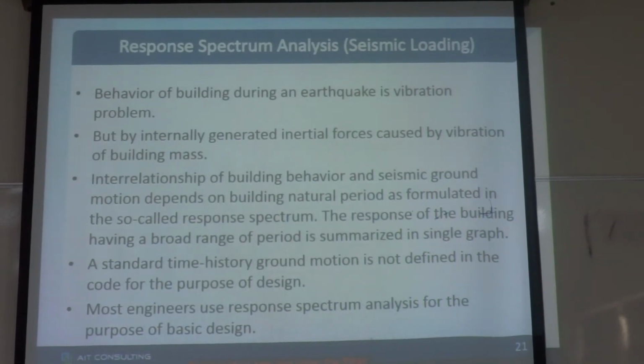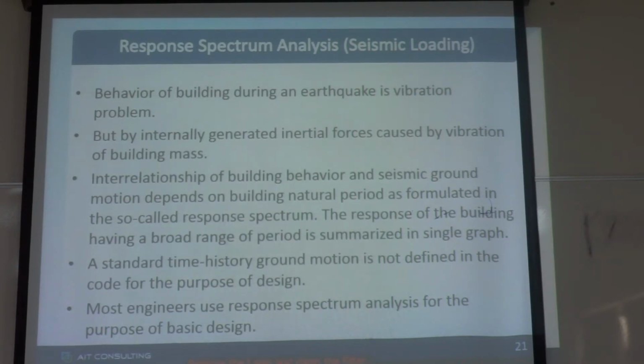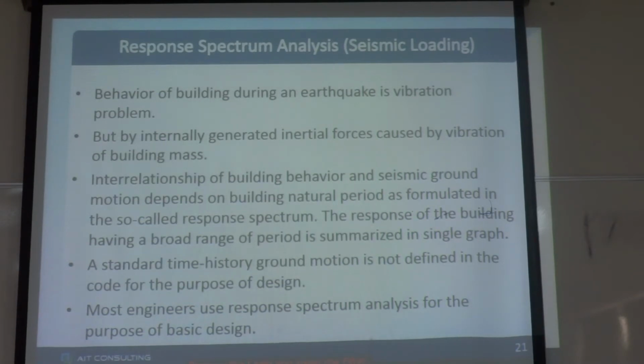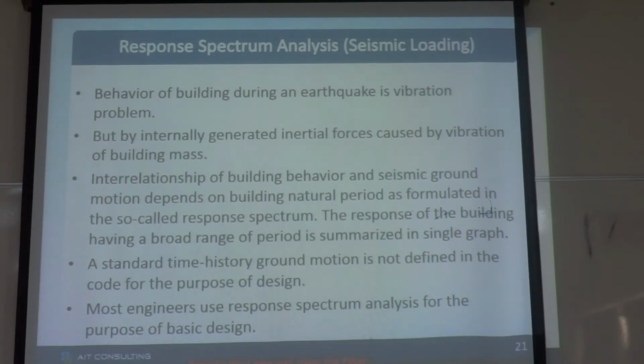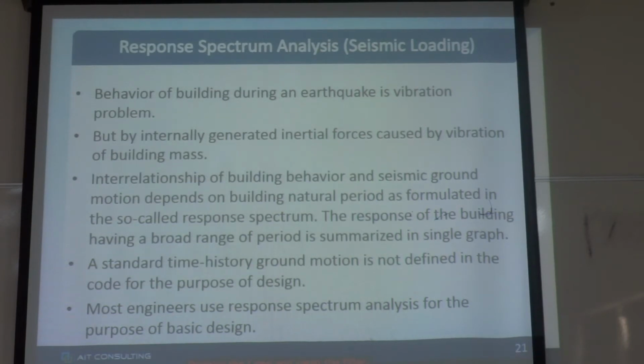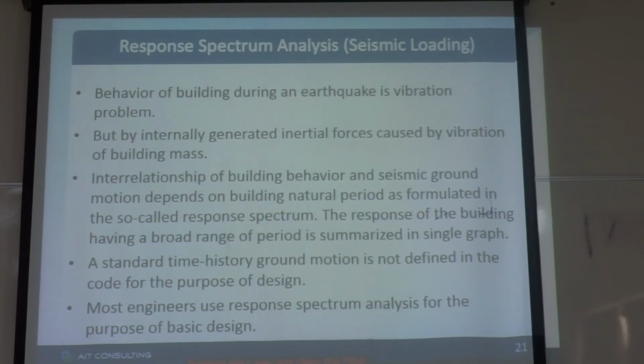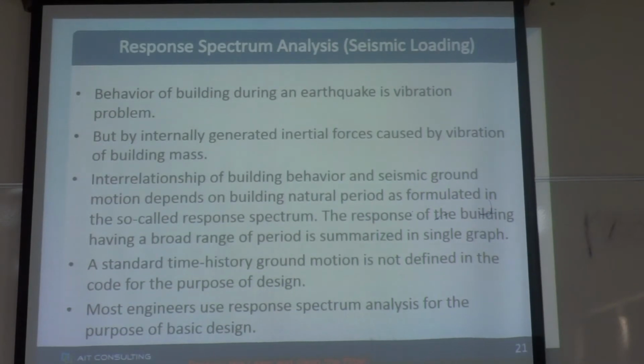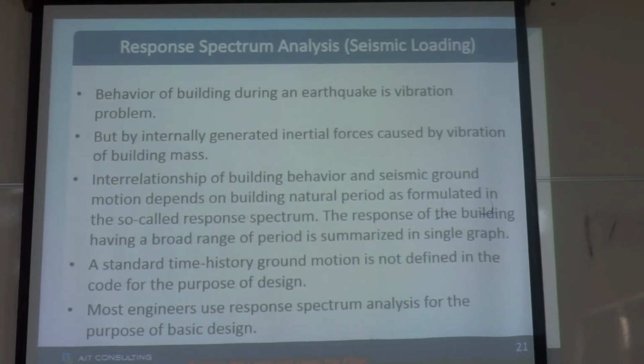This is response spectrum analysis. For seismic analysis, the behavior of the building is due to the vibration. These are the internally generated forces due to the building mass, and also the ground shaking, and these forces depend on the shaking of the ground and the stiffness of the building.